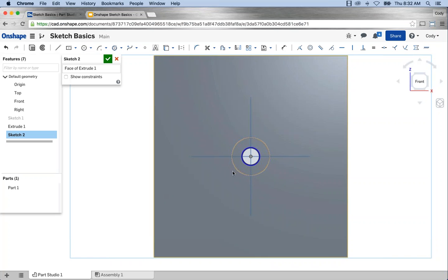And then I add another dimension, define it the same way, right? The problem with that is how it updates, and this is something you'll realize as you start getting more into it. When you make a change to one feature, if it's not tied to the others, if you have a whole series of redundant dimensions, then it doesn't update well. You'll need to go through multiple sketches to get it correct. So the reason I'm bringing this up is the use command.